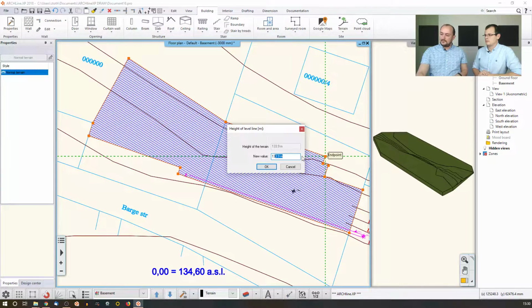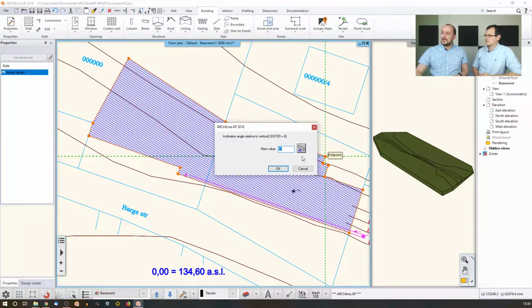That will be the 0 level for me now, because I will use it as a flat ground for the building, for example. So I just say, okay, this is at the same specific level, and then now I need to set up the slope. Now this area is obviously not the same as the terrain, so someplace I need to extend it, and someplace I need to cut into the terrain, and those slopes are the things that I'm about to set here. If the slope is 0, now in case of a terrain, when slope is 0, it's not horizontal, it's vertical.